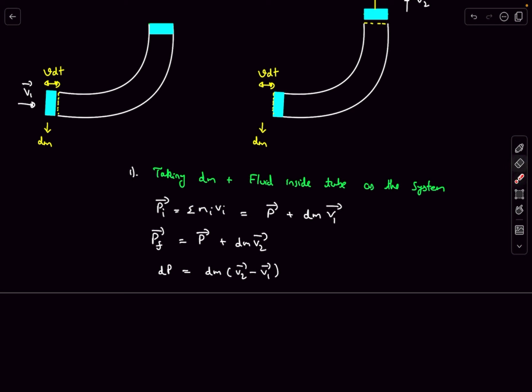So what we did so far is figure out the small change in momentum in our fluid system. The small change in momentum of the liquid is also the impulse applied on the liquid. An impulse I can write as f times dt, as we are talking about a small time interval dt, where f is the total force acting on the liquid. When we write impulse, we write impulses due to all the forces. So this f vector is the net force acting on the fluid body, and that times dt gives us the impulse acting on the fluid.